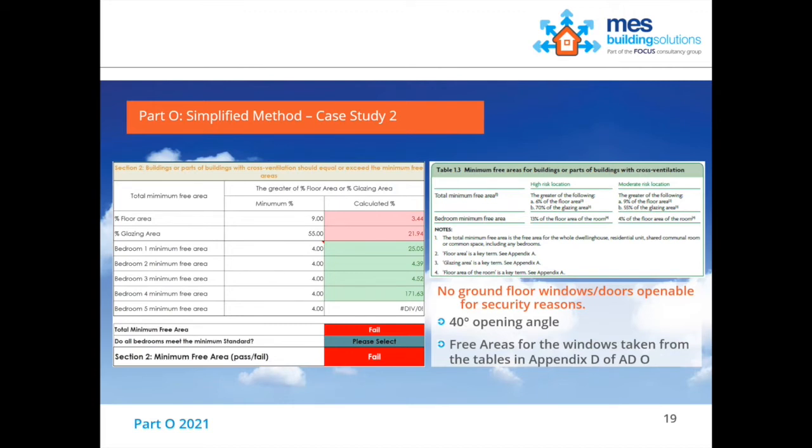You look at that and you'd say, well, I know which areas of the building are likely to overheat: the ones with all the glass in them that face south. And that's really what this is confirming. We need to do something about the glazing in that space.